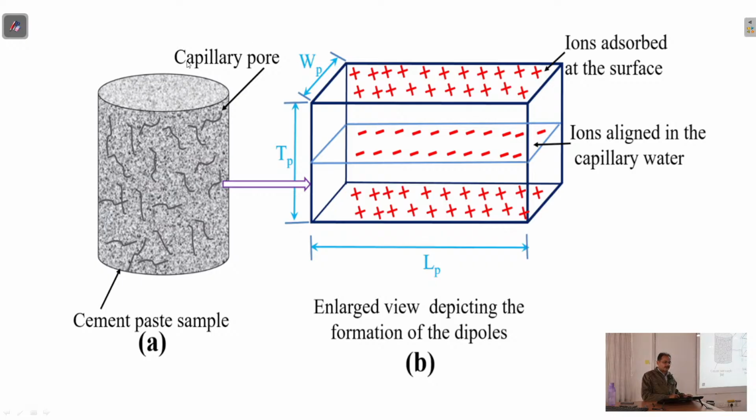So what is considered is, suppose a load is applied on that, then strain will be produced. Say there is some compression, then what will happen? The sample gets compressed. So we just assume that as this compression takes place, these capillary pores will also undergo compression. Of course, at the micron level, the same thing will not translate exactly, but we went for an approximation. So we considered that whatever strain is produced for the bulk sample, we can translate the same to the capillary pore also.